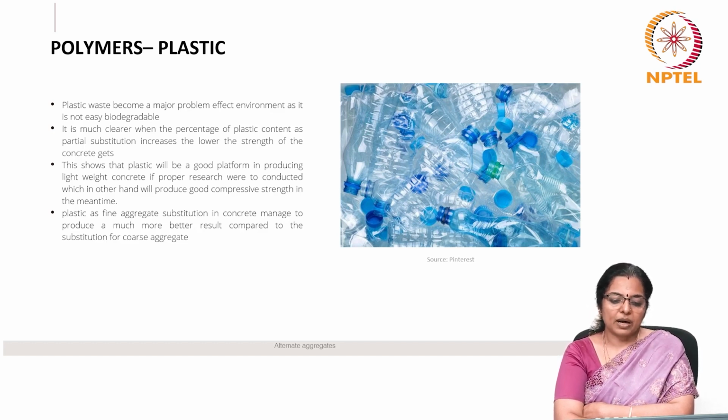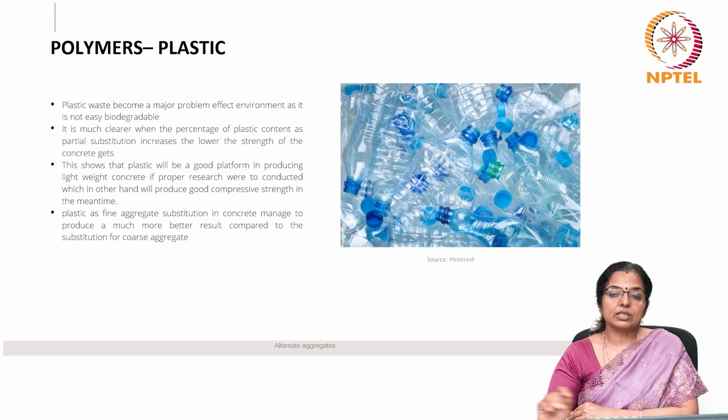This shows that plastic will be a good platform in producing lightweight concrete if proper research is to be conducted, which on the other hand will produce good compressive strength in the meantime. Plastic as fine aggregate substitution in concrete manages to produce a much better result compared to the substitution for coarse aggregates.